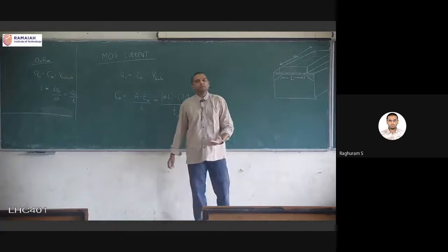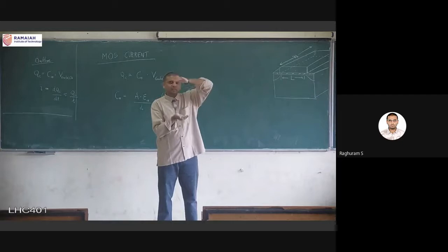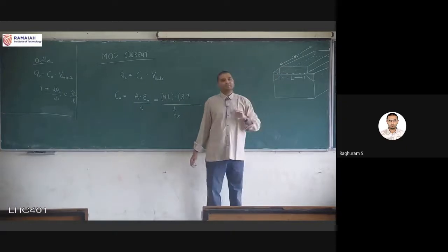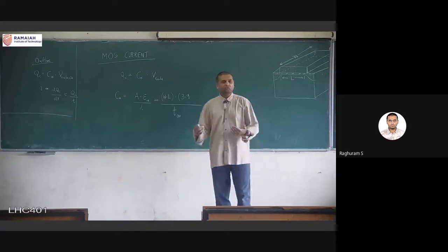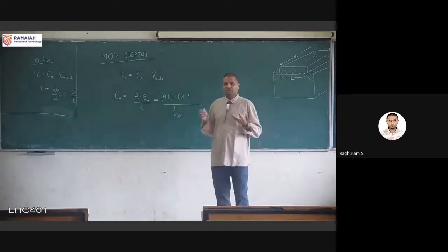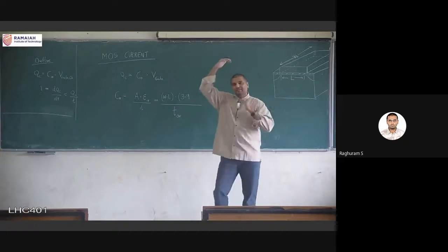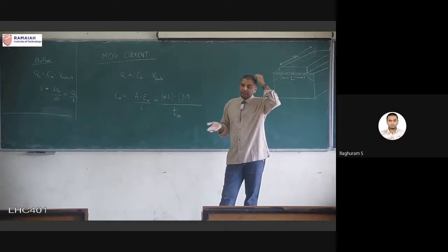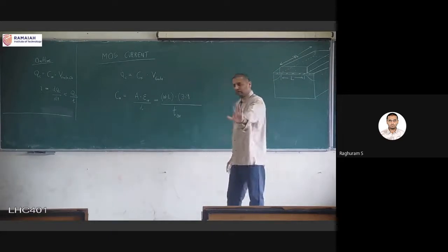So some people have tried increasing the thickness again, maybe going from 2 nanometers to 10 nanometers. But to get good control, they have shifted from silicon dioxide to a different material. It's not very easy to randomly choose a material, because fabrication is a very, very complicated process, and all the components have to be compatible with each other. The silicon has to accept whatever you are putting on top of it. If it doesn't like it, then you can't make the transistor. So after a lot of research, they found that hafnium dioxide was working well. Some people make it, but let's not worry about that.